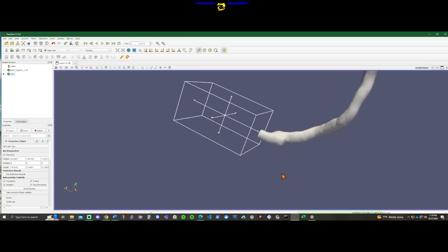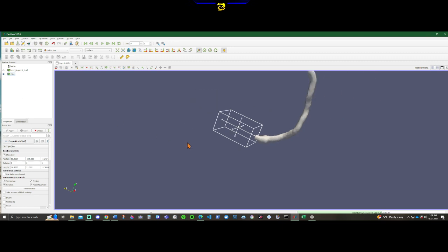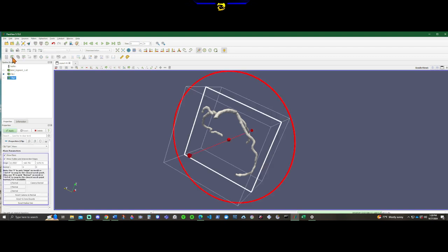You don't want to nest any more clippings, and you don't want to basically hide the existing. I know I did this a lot when I started. I didn't really understand how it worked, but each clip is going to be its own separate box. So again, while you have the next clip selected, you clip again to keep the old clip intact.